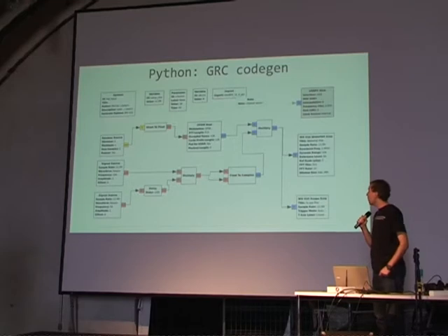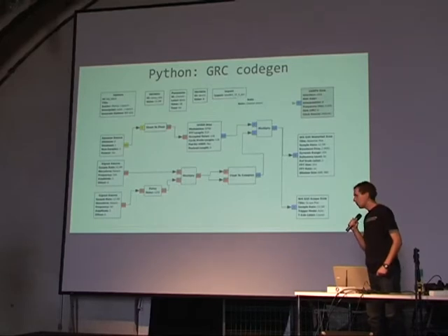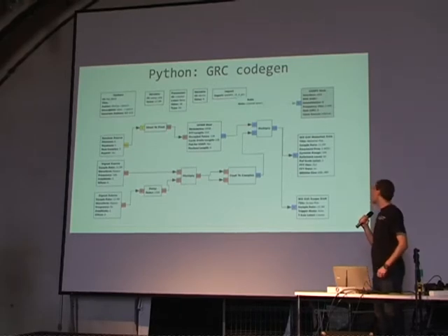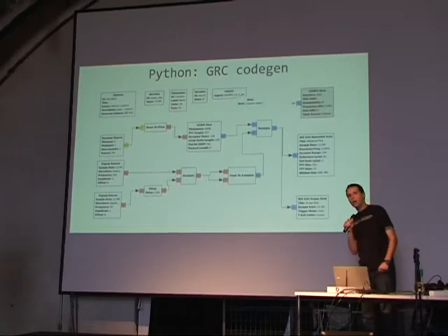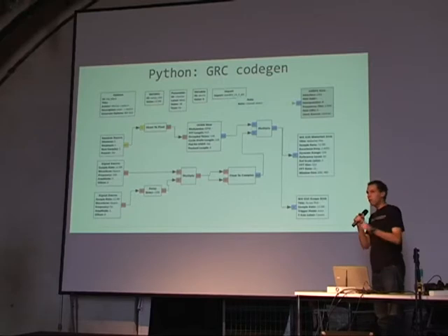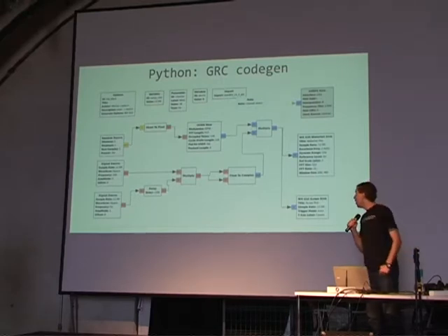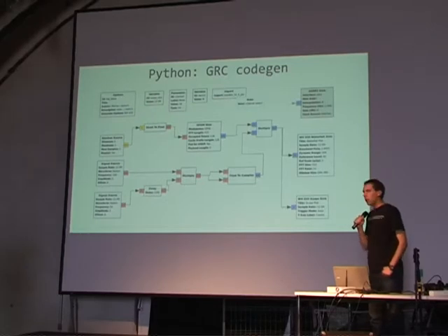And this OFDM modulation uses QPSK, which has 128 occupied tones, which generates an OFDM QPSK signal of bandwidth of 4 megahertz. And since one IEEE 802.15.4 channel is 5 megahertz, it can actually disturb one entire channel. And with the parameters for gain, you can define the intensity of your interference.